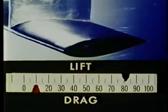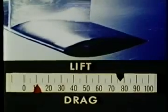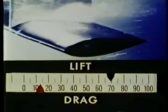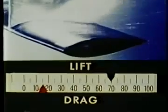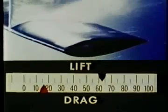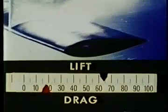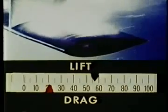The flow speed is constant, and the gauges register the corresponding lift and drag. The ambient pressure is set at a level well above that at which cavitation can occur. We are going to induce cavitation by decreasing the ambient pressure in the test section, keeping the speed constant. At first, there is no appreciable change in either force. As cavitation develops, lift decreases and drag rises. You can see from the force balances that the flow is quite unsteady. When we lower the pressure further and allow cavitation to spread, the lift decreases further and the drag continues to rise.